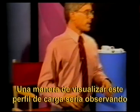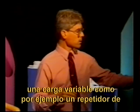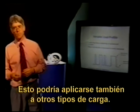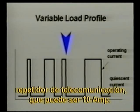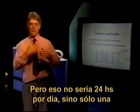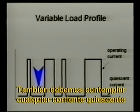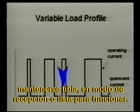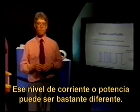So one way that we can visualize this load profile or this variable load would be to take a look at, let's say, a variable load like maybe a telecom repeater. This could apply to other types of loads as well. There might be a specific load demand level for a telecom repeater that might be 10 amps. But that wouldn't be 24 hours a day. It might only be a certain fraction of the day, maybe a few minutes in the day. We also need to look at any quiescent current or standby current, where the load might be simply kept warm or kept in receive mode or kept ready to operate. That current level or that power level might be quite different.